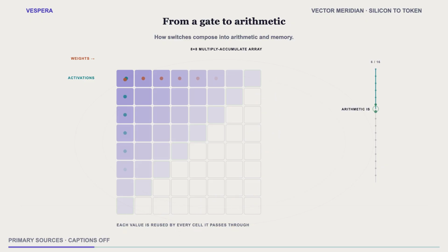Essentially, all real adders use a cleverer structure that computes the carries in parallel, carry look ahead, and its descendants, trading more transistors for less delay. This is the first appearance of a trade that recurs at every level of this subject. Spend area to buy time.